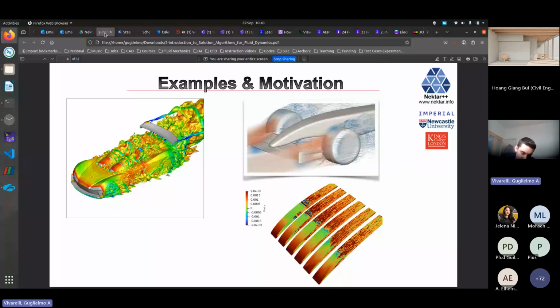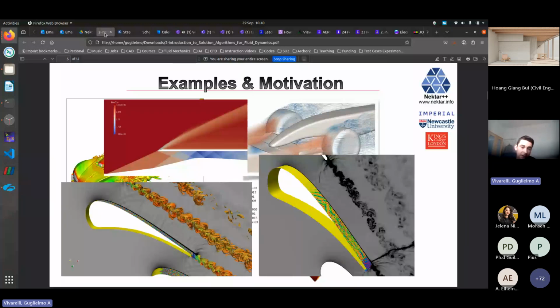So there's always this kind of gauging what is the cost and what are the flow conditions and what sort of resources I have. And then there are cases where I can't do anything else other than utilize the compressible flow solver and have significant resolution to try and capture the flow physics correctly. And as you can see on the top left-hand side, an intake with shocks forming with reflections, of course, and then on the bottom left-hand side, a high-pressure turbine, which has been my work over the past 3 years. And you can see in the grayscale image at the back, the pressure waves forming in between blades, traveling from the trailing edge of one blade to the suction side of the neighboring one.